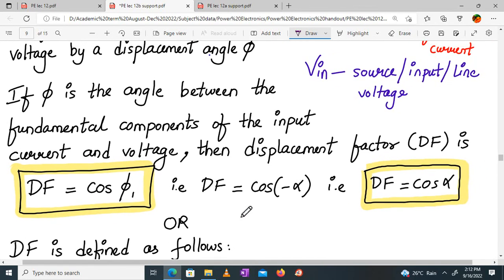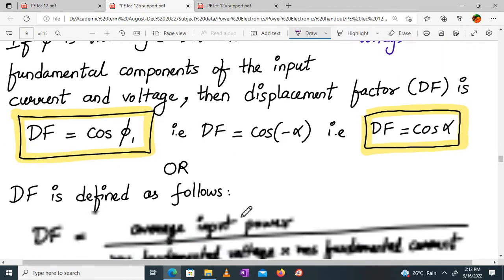Alpha and phi values equal, yes, you can say that. Yes, you can say that. In this case, it might be equal in magnitude but opposite in phase. Actually, yes, they will not be equal. If they were equal, the harmonics would be reduced. You filter out the harmonics. Actually, what happens is we normally pass it through filter circuits and then we try to remove the harmonics. So the closer the firing angle and phi are, the better. Ideally. This is an alternate derivation, but it leads to the same result. So okay? It's the same.